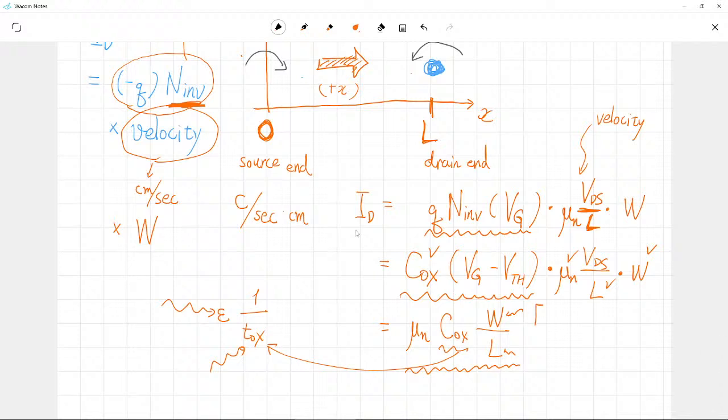And after all of this geometric consideration or material consideration, now we have the real electric part. The electric part is simply given by what? Vg minus Vth, and finally Vs. Now, after a long discussion, we have arrived at an expression for drain current. However, please note that this is not a correct expression. Why is it not correct?